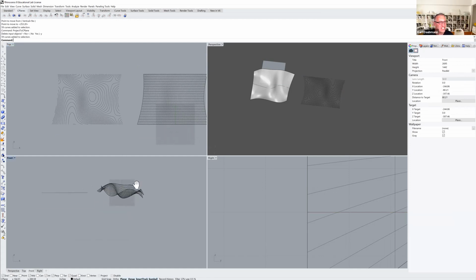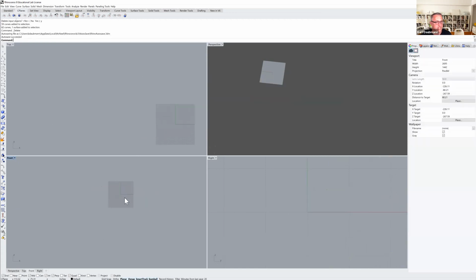Yeah. So I would, and we'll do it a couple of different ways too, because in this case, if I do it once more, you can work in either the front view or the right view, but I would draw a control point curve. Just so you get a sense for the control points and how to draw a curve like that too. But I would do kind of opposing curves. And then maybe the third curve is just a more simple arced curve through there.